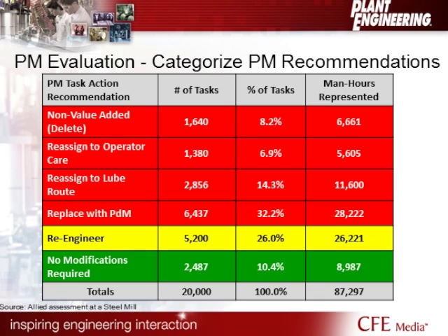Now you see 32% of the PM tasks in this facility needed to be replaced with PdM. So the great thing about using the predictive technologies like PdM is that, just in case everyone's not familiar with the predictive tools, let me list those for you. So the big five that we talk about: vibration, infrared, oil analysis. We also talk about motor current analysis and ultrasonic. So those are some tools that we might use to really begin to see defects at the early stages. The great thing about those tools is they're used while the equipment is running in many cases. In fact, in most cases, all with the exception of maybe MCA, offline.